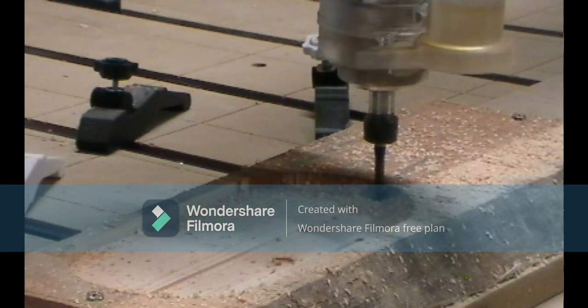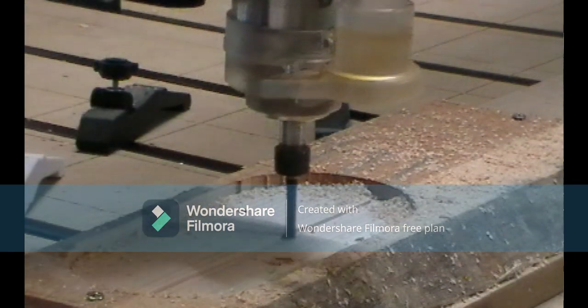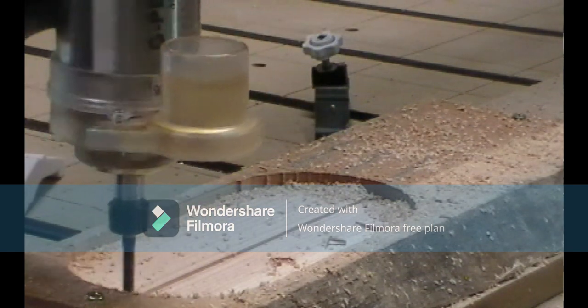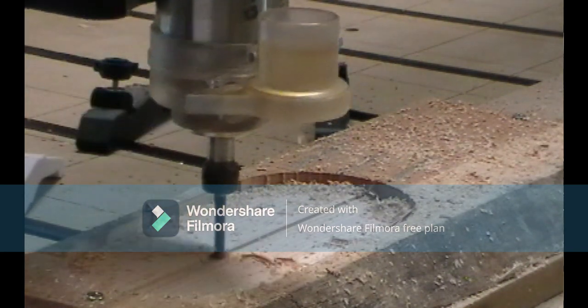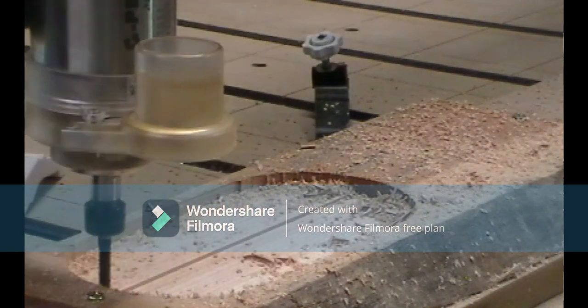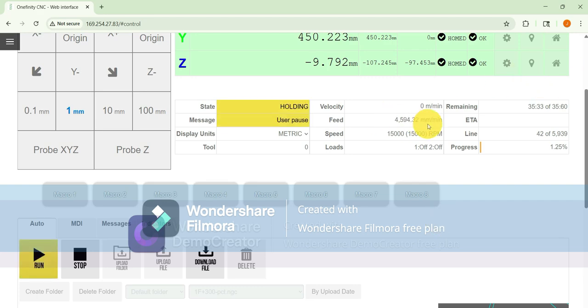As you see, the spindle has moved, and now it is moving at 45.94 millimeters per minute. I probably need to slow it down just a little bit because I'm only cutting 2 millimeters deep. So let me go ahead and pause it. We'll stop the spindle, and we're going to decrease this by 1,000. That would be around 20 or 30%, so we'll just say 30%.